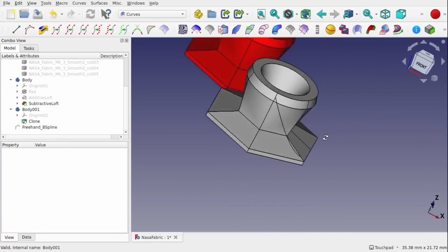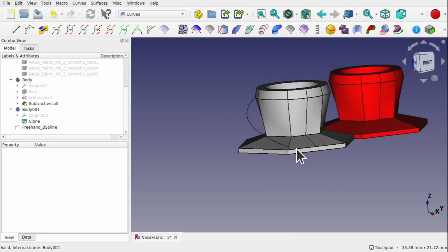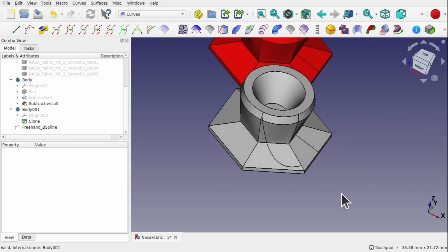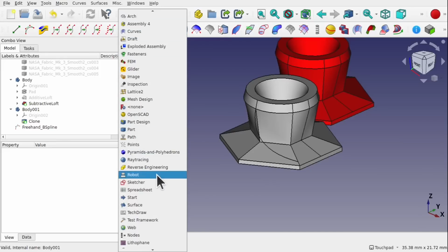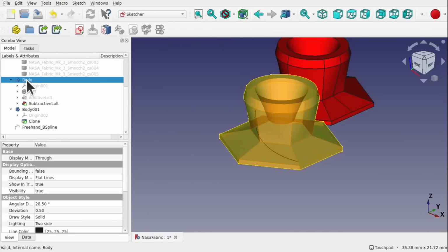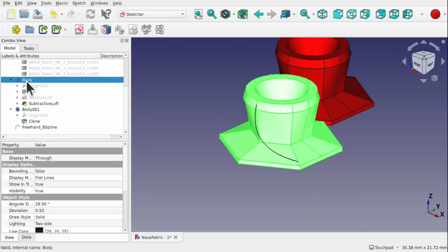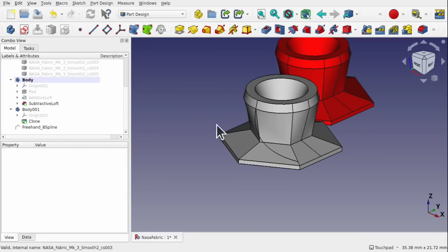But we may get into some problems, because if we follow this path, then we're following it down, and I need to intersect this shape. So I may need a number of profiles to actually shape this. Let's start by creating our first profile over in the Sketcher workbench. Make sure that the body, at the moment we can see it's not an active body, it's not bold. We right click, toggle active body. This means any sketches will be created inside this body, which we need.